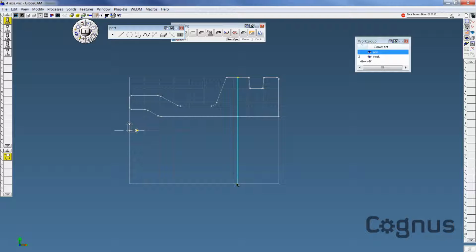This machining marker does 3 things. On which side of the geometry is the tool going to travel? I'll pick on this circle. The blue arrow is the direction of cut. It is already set. And thirdly, these white and black markers tell the system where the toolpath starts and stops. I'll hit the Do It button.